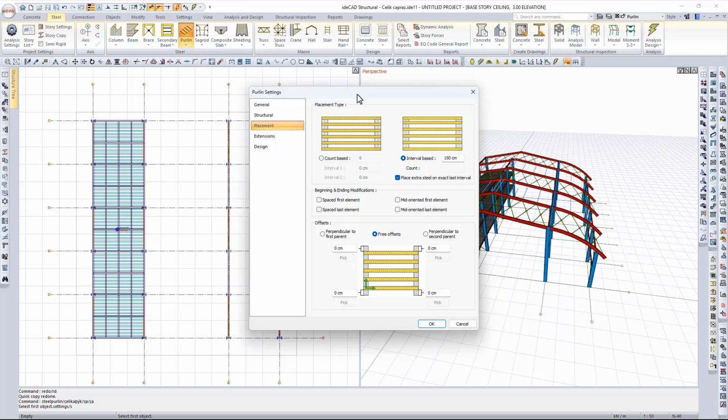If you use the secondary steel beam command for roof geometry, you won't be able to place sheeting, and no load transfer will occur. Although the logic is similar, you must use purlin and sheeting on roofs and tie and sheeting on wall facades. For intermediate floors, combine the slab command with secondary steel beam or steel beams so the software can process load transfers correctly.